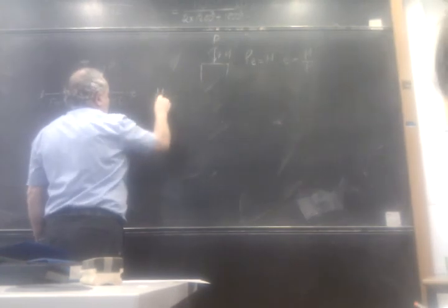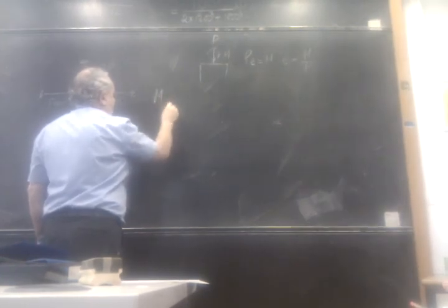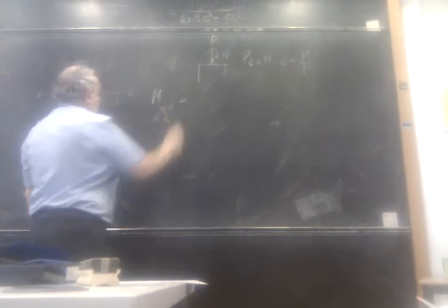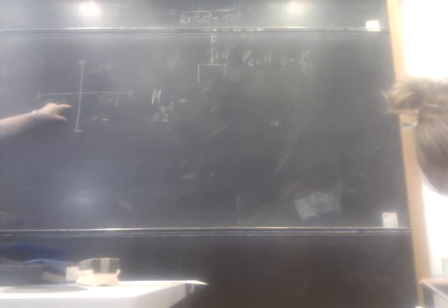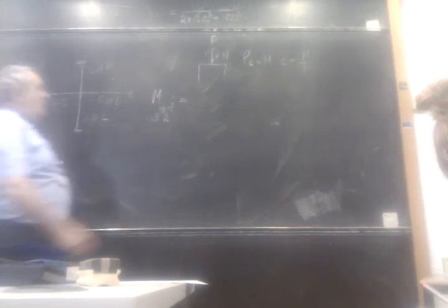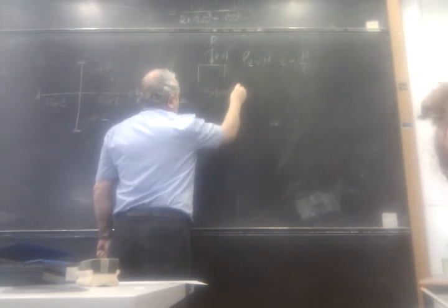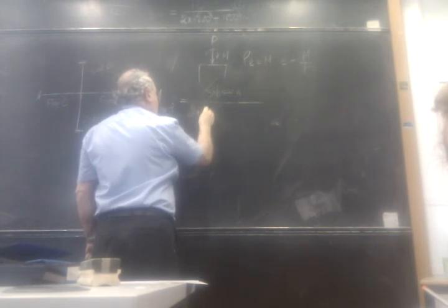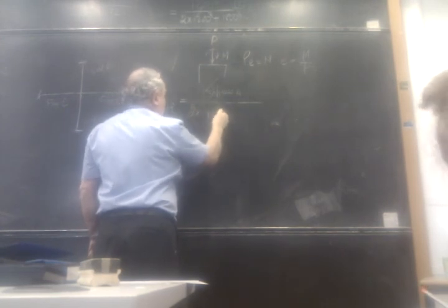So the moment at the top of wall A is the stiffness of wall A divided by the sum of the stiffnesses there. So it's stiffness for wall A divided by 2 times stiffness for A, because we've got 2 of them.